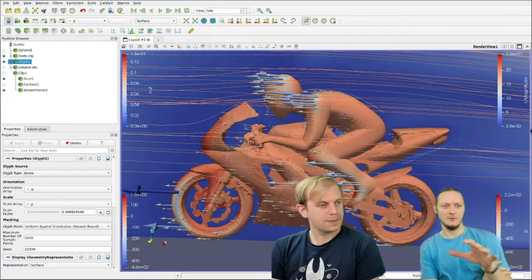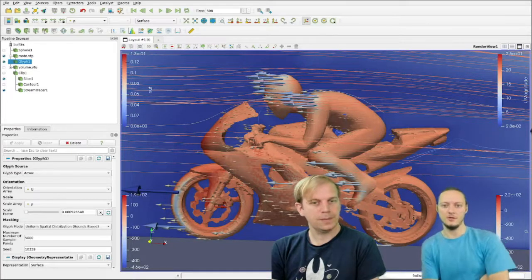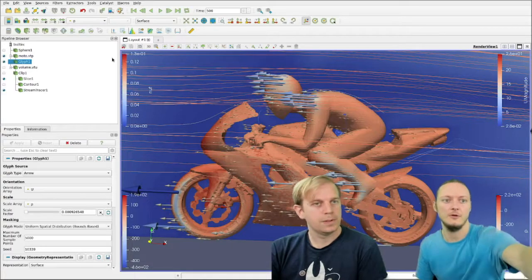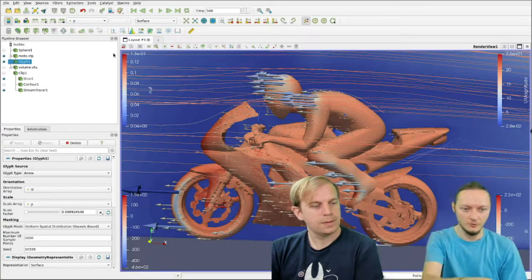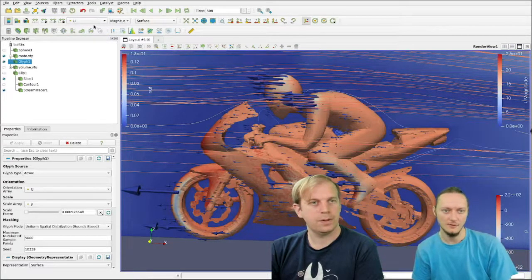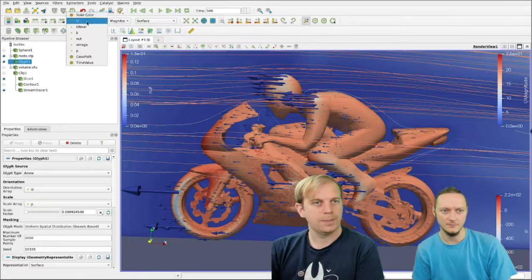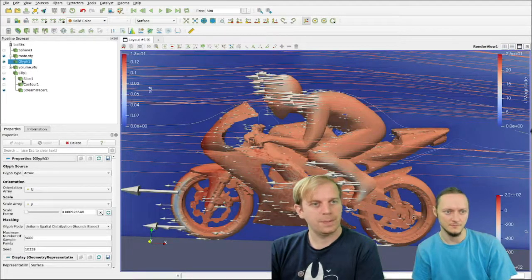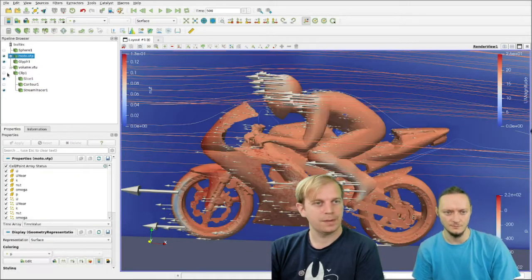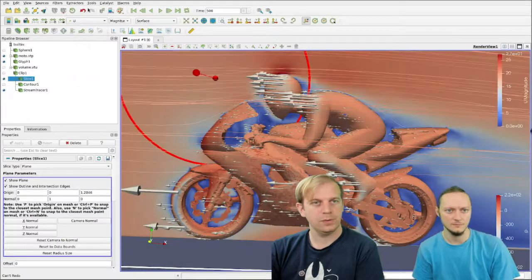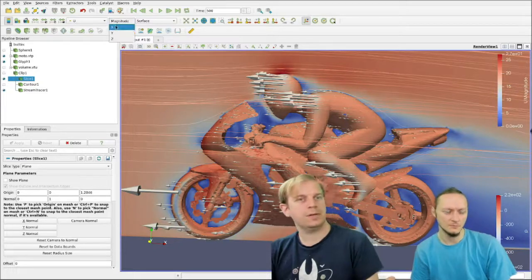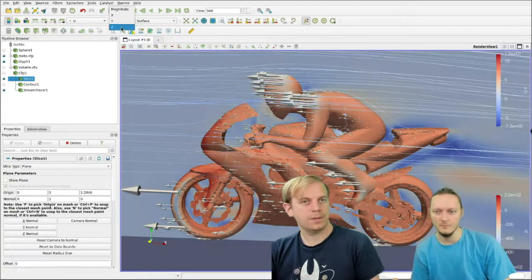And in terms of scalar value, I mean, in color on the screen, can I show some vector? What do you mean? Sorry. If I want to have vectorial data shown on the screen, for example, if I want to show U as a color array for my data. Sure. You can just, well, U is not great for the glyphs because U is uniform here. But let's show U on the slice, something like that. Here you can show U like that. Let's hide the plane, and when you show a vector, you can select the component if you want. Like that.